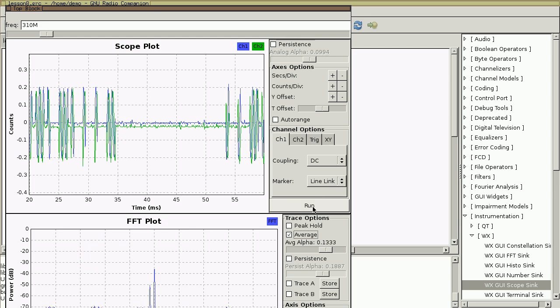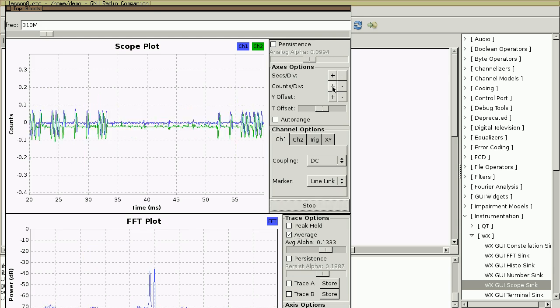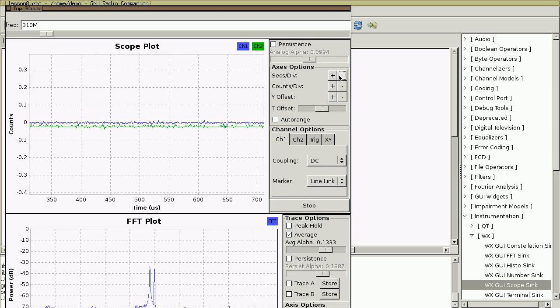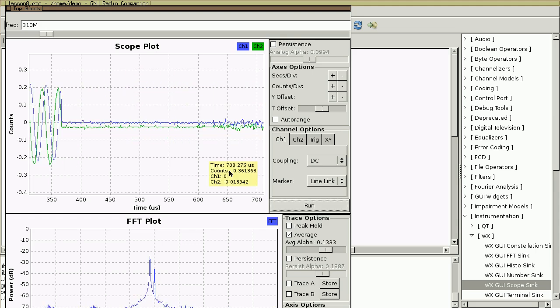And if we were to look in the scope sink and zoom back in again on the time axis, you can see that every time we see this sinusoid, it looks quite consistent, right? Every time it looks like it has the same period every time it shows up here. Those are two indications that this signal isn't changing frequency over time. It is changing its amplitude to extremes. It's being shut on and off.